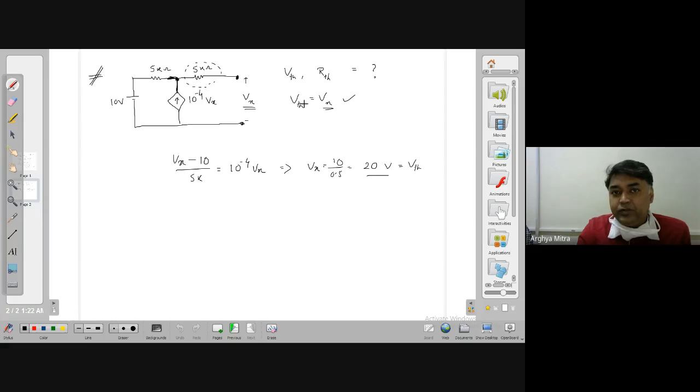Okay, because the reason is that the value of this voltage source or the current source depends on the branch current or the voltage. So any branch current or any branch voltage determines the voltage and current of this particular source. So when we are neglecting the independent sources, then it's fine. But you are not neglecting any branch of the network.